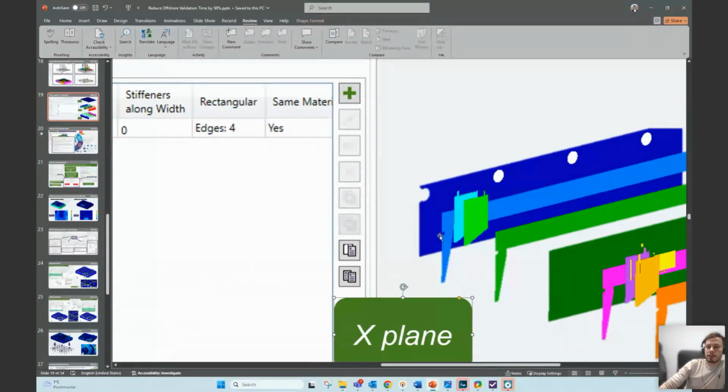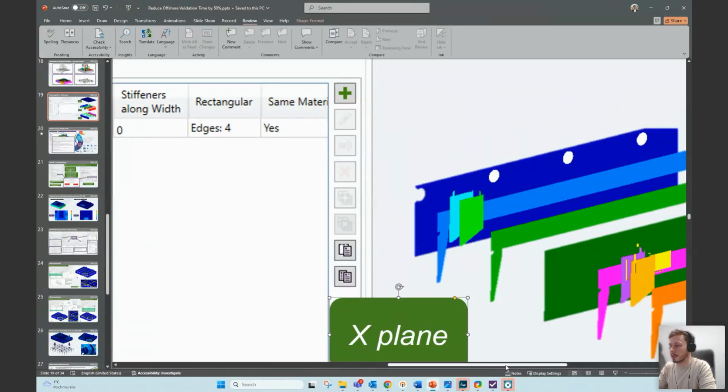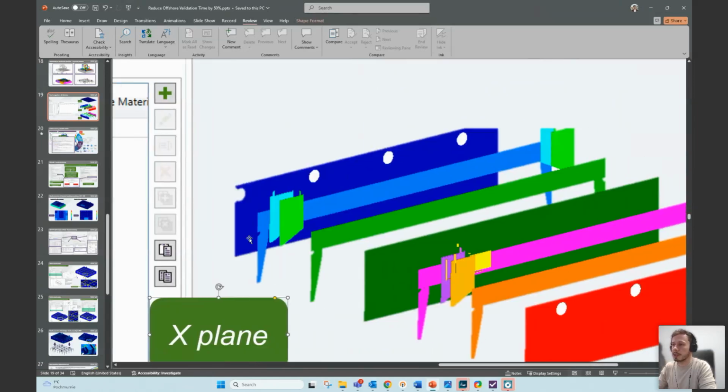In SDC, we give you the possibility to adjust the settings so that you can set the percentage value of the plate which is covering another plate. For example, if 80% of this plate is intersecting with a perpendicular plate, it will be recognized as an intersection. So there is the possibility to set this value.